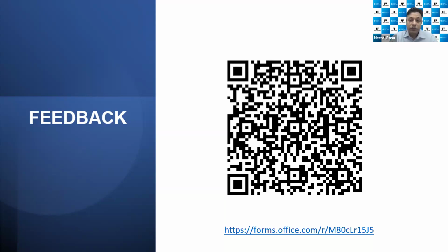So you have both conversions. We can use the width and the GSM of the fabric and then the kgs, and then we can estimate a length. At the end, it's an estimation. And then you can track the actual from the shop floor. The estimation was, let's say, 50 meters out of that 35 kg roll. But when it comes to the shop floor, we come to know it's not 50, it's less. So you can correlate that.